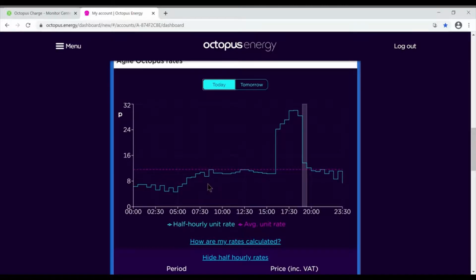Now, what we also do is, as well as setting a nighttime and a daytime charge, what we strongly recommend people do is use the monitoring platform also to block discharging. So for example, on mine, I say, right, from midnight till 6 o'clock in the morning, yes, I want you to find the 4 cheapest and charge, but I don't want any power coming out of my batteries. I want them sitting full, come 6 o'clock, ready to run my house.